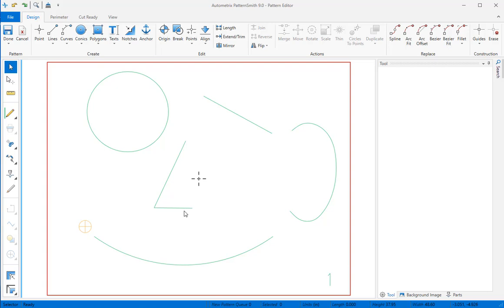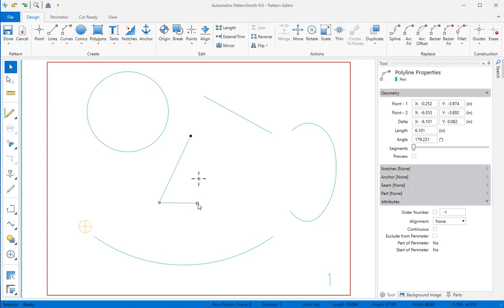So the only difference between snapping a point or snapping an entire selection is the order in which you press the snap key and the mouse button. Press the snap key before the mouse button to move an entire selection. Press the snap key after the mouse button to snap a single point. You can use the snap key and the constrain key when you're creating elements or when moving points and elements.